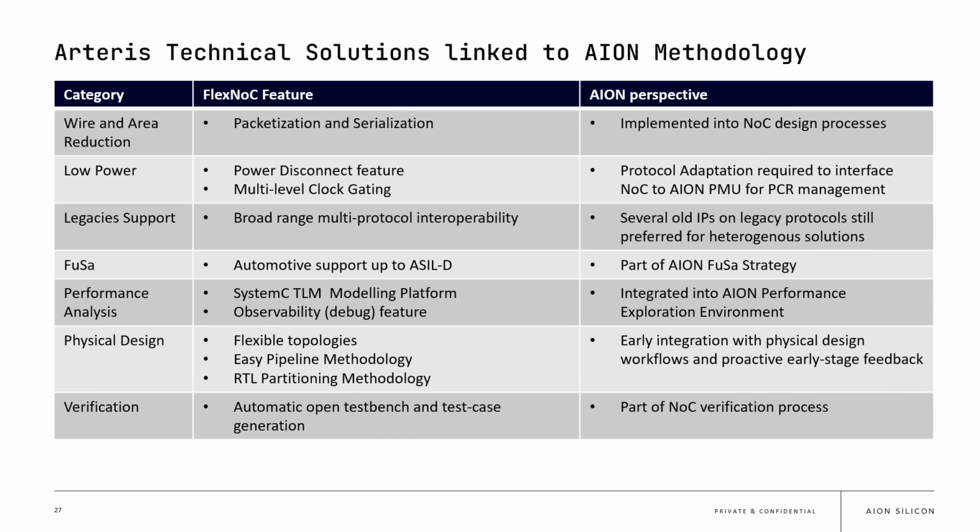Thanks for that, Andy. So now I'll cover briefly how Arteris technical solutions are linked to AION's methodologies. In terms of wire and area reduction, we've got the packetization and serialization feature, which have been implemented into the NoC design process. And also on low power, we've got the power disconnect feature and multi-level clock gating, which we've implemented as part of the platform management unit and power clock reset strategy.